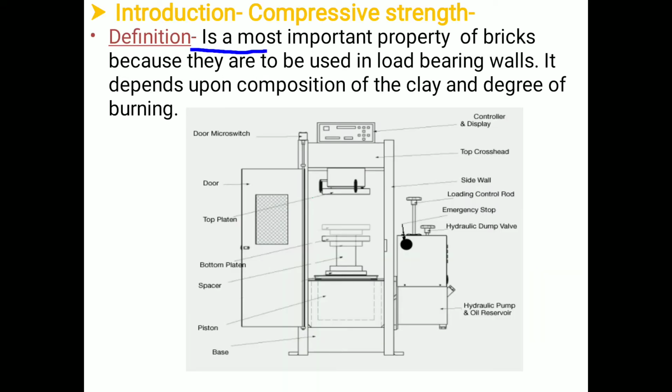It is a most important property of the brick because bricks are to be used in load bearing walls. All of you know that brick can be used for the construction of load bearing walls, pillars or arches. So when it is used in such cases, it is subjected to compressive stresses. So it is very important to determine the compressive characteristic of the brick.